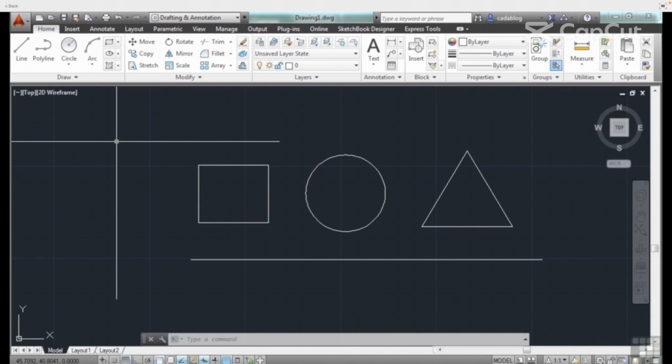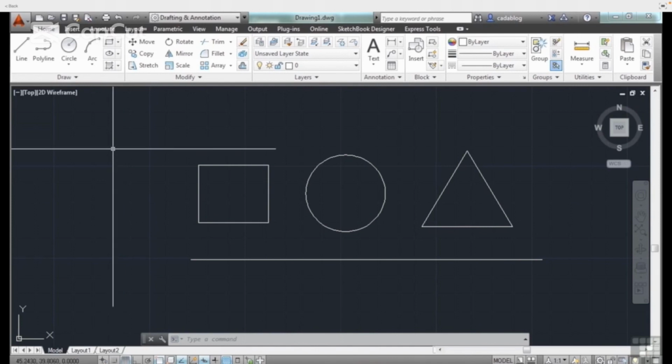You create your drawing objects or your model in model space. They can be 2D or 3D objects if you're working with AutoCAD. Then you switch to paper space and add your drawing border and your title block. Then you add your notes, your dimensions, your text, your details, your callouts, etc. Paper space is for your annotation, especially so if you're going to create more than one sheet in a file.